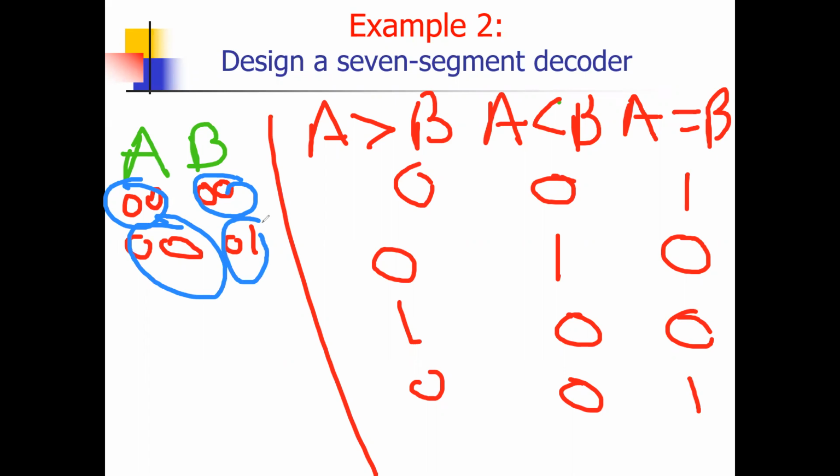Clear? So in the exam, we can give you a maximum of a 2-bit comparator circuit, because for a 2-bit comparator circuit you are using a 4 variable K map. I cannot give you a 3-bit or 4-bit magnitude comparator circuit. In the slide which you have, there is a 4-bit circuit, which you cannot solve using K map. I just added it to show you, but we cannot give it to you, because for this implementation you cannot use a 4 variable K map.